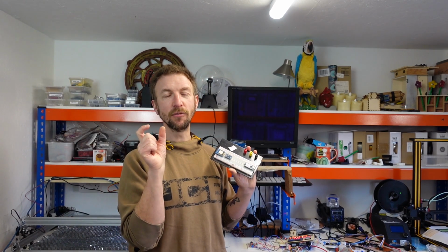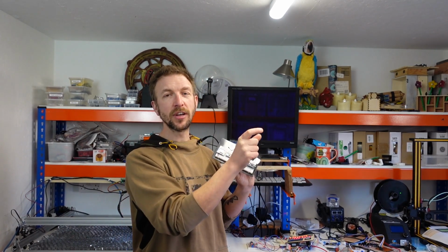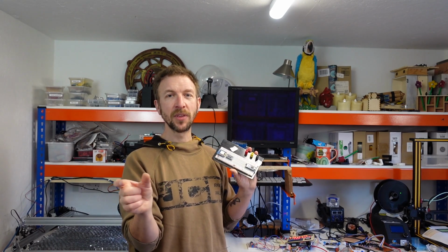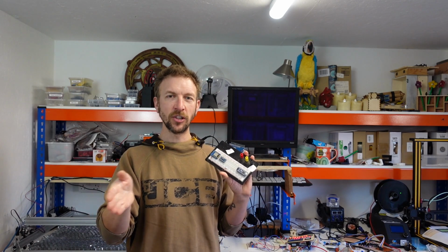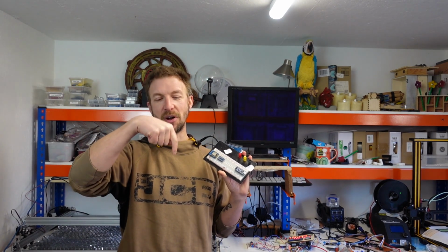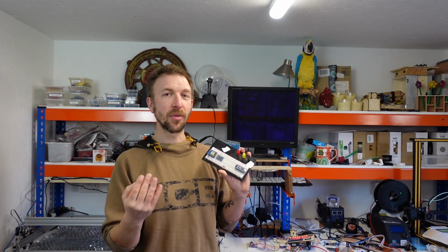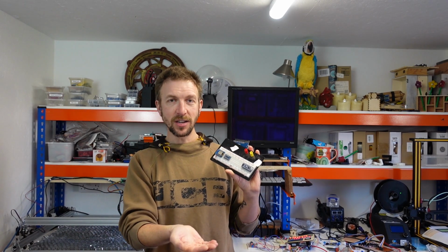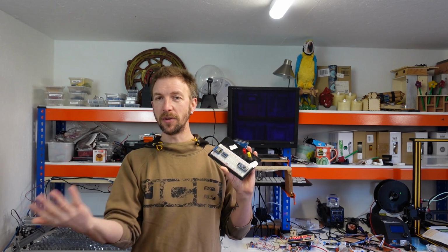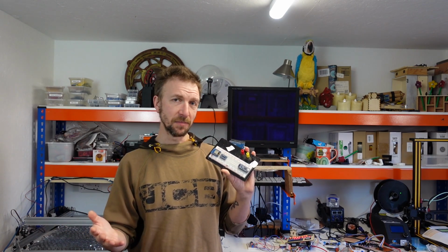If I create a resistor divider with a 2 kilo ohm resistor and a 1 kilo ohm resistor, that's going to split that signal into 2/3 and 1/3 of the voltage. And if I read off at the midpoint of those, that will give me 3.3 volts, which would be fine. And on the transmit line, I can send out 3.3 volts and it'll be read by a 5 volt signal as high, so that's just fine.